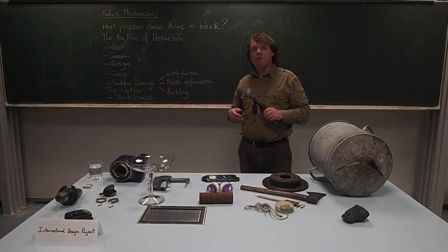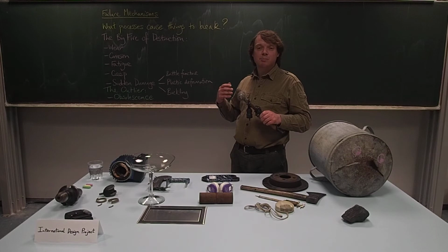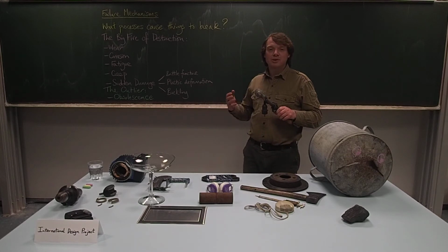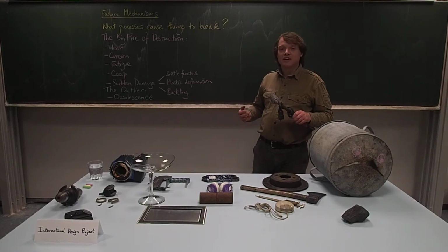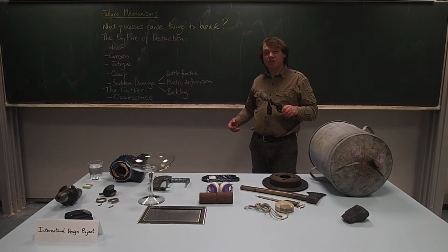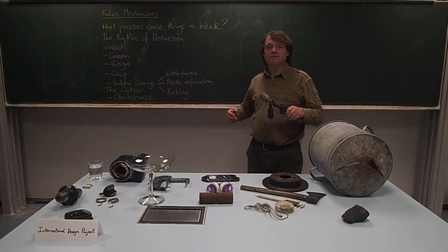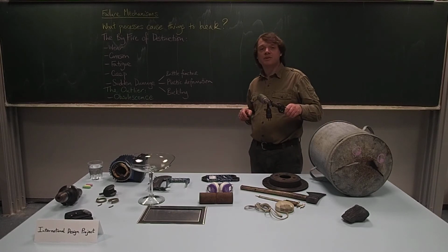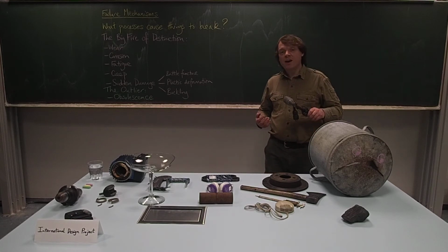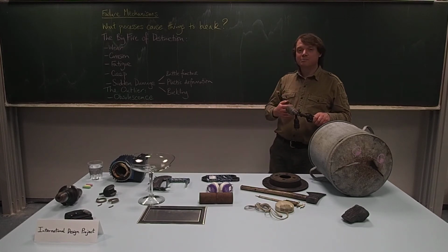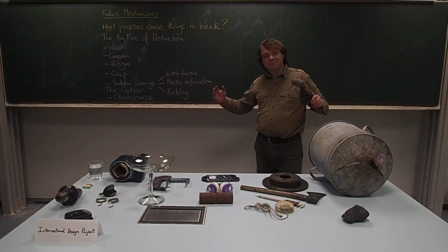You'll find that's more often a problem with low voltage equipment, because there isn't much of a spark to jump across the oxide layer and burn through it, and everything needs to have a very low resistance for it to work. So you'll find with things like a welding set, sometimes the earth clamp, if it gets corroded, will no longer work, or in a vehicle, if the battery post terminals get corroded, especially if it's an old vehicle with a 6-volt electrical system.